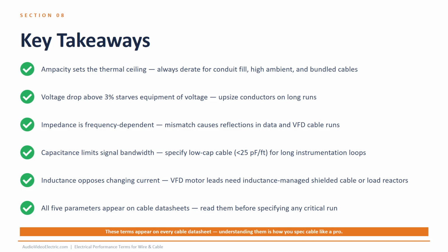To summarize, ampacity sets the thermal ceiling. Always derate for installation conditions. Voltage drop above 3% starves equipment. Upsize conductors for long runs.